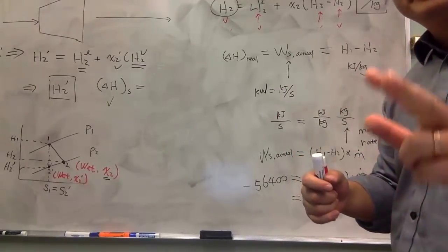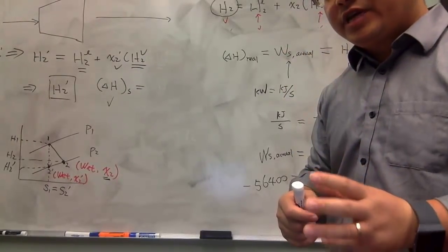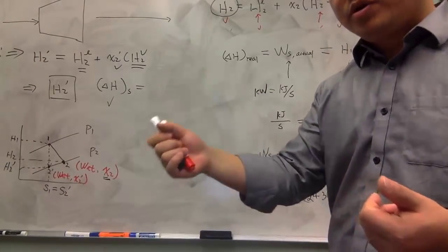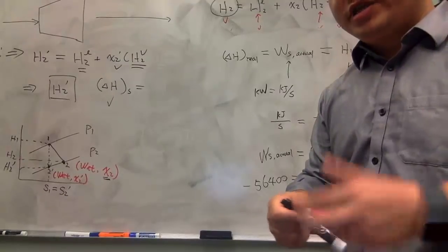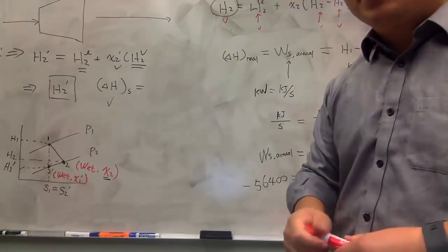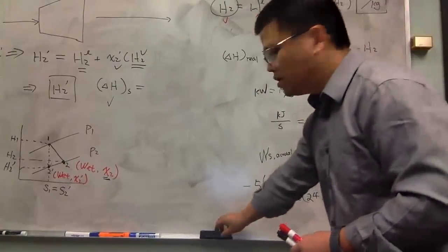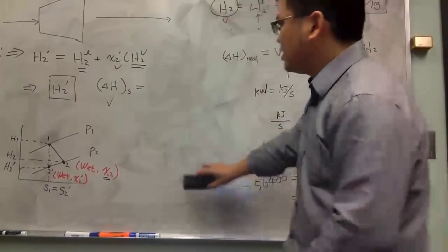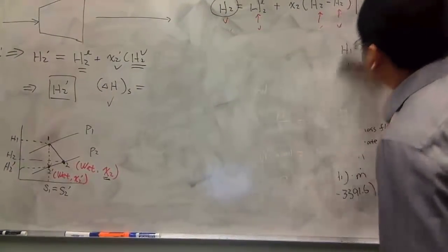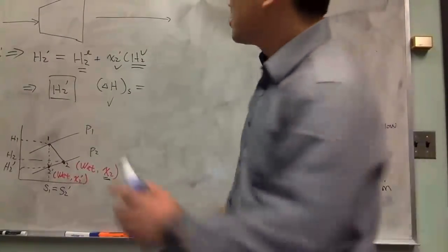And we need to figure out two critical values. One is along this isentropic process for that wet steam, what would be the ratio of vapor and liquid. And we also want to have this same ratio for the actual final state too. And by having a clear understanding of the final, then we can manipulate all sorts of questions. To somehow summarize the flow of the calculation, I'll try my best to describe a general procedure.